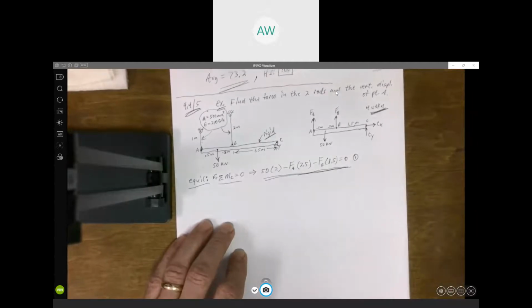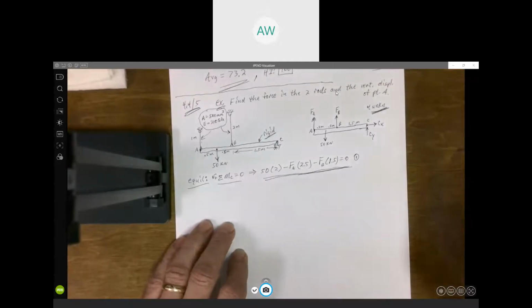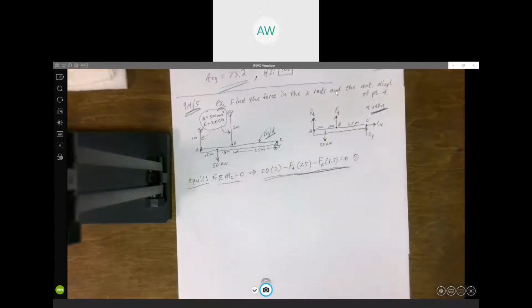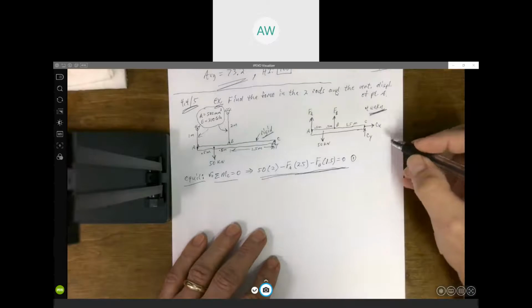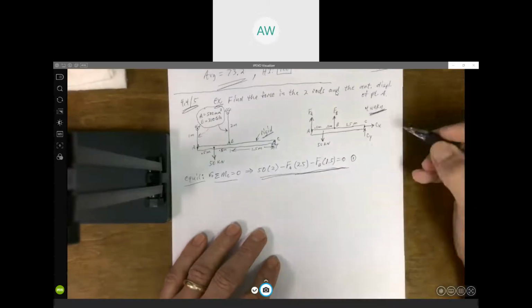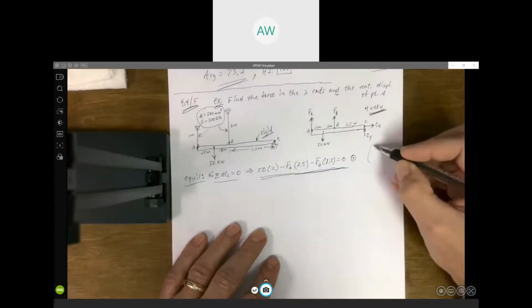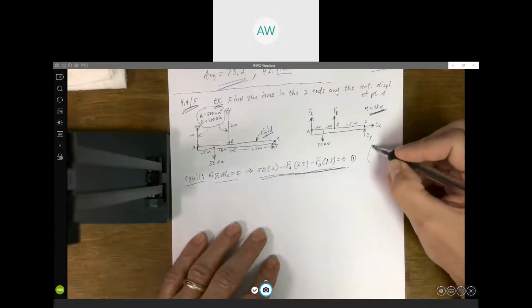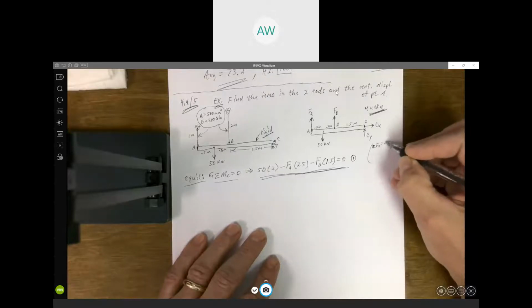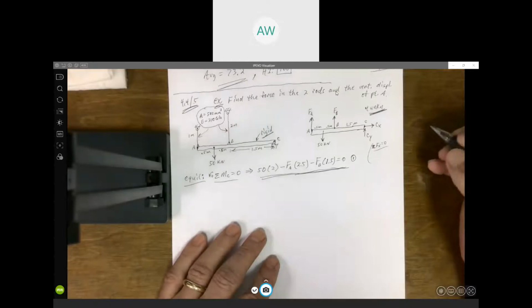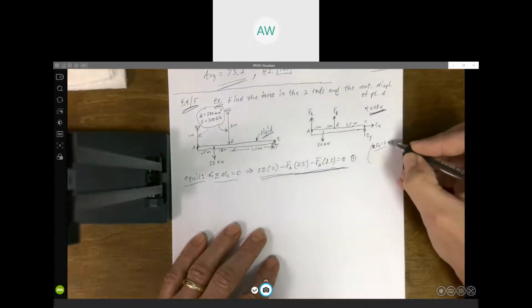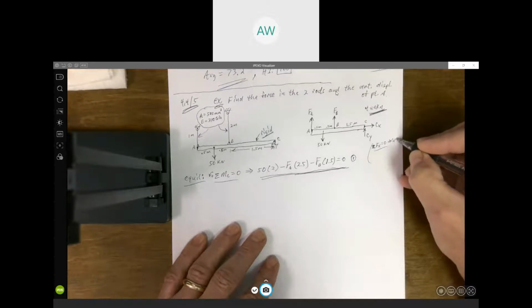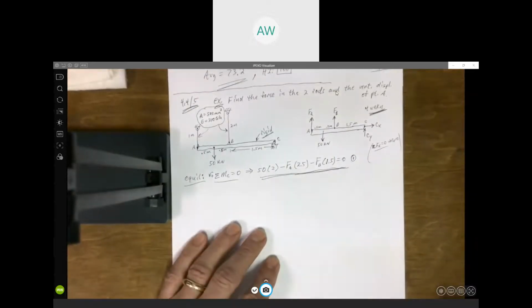Notice here, summing the forces in the x and y direction is not going to help us. Again, you don't have to do this, but I'll just write it to the side, just FYI. Summing the forces in the x direction, right? All that's going to tell us is what? Cx is 0. Which is okay, but not really needed.